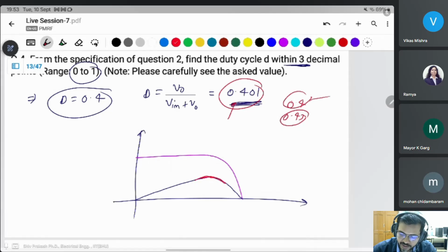You don't want it to oscillate like that at the maximum power point. It will go below this point, then after you sense the next sample of voltage and power, it will return back. Then it will oscillate again. But if you give a more accurate value like 0.4321, then it will oscillate around the middle point only.